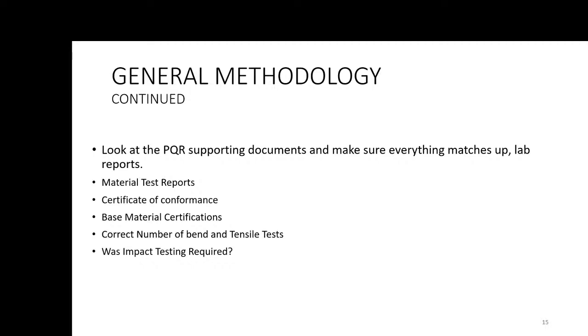So now we're still going through our general methodology, how I approach this. Somebody throws a stack of these on your desk. Well, now it's usually email. But look at the PQR supporting documents and make sure everything matches up. Make sure all your lab reports are there, material test reports, COCs for filler material if they're required, base material certifications, correct number of bend and tensile tests. Make sure those have been done.